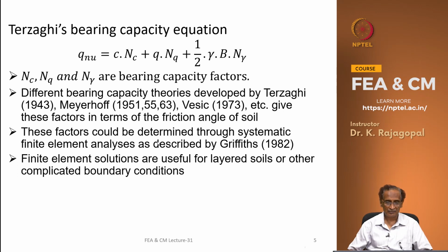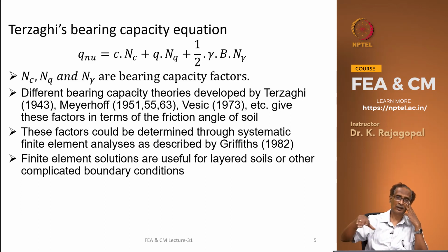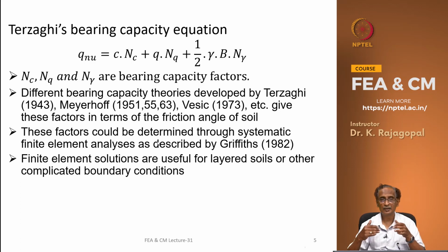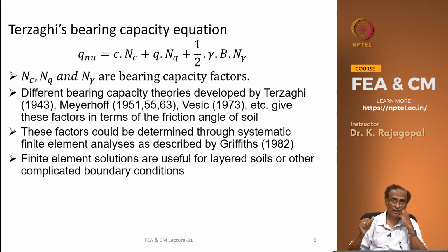And this finite element analysis becomes necessary if you want to analyze a layered soil profile, or let us say your soil profile is highly complicated. You have inclined soil layers and some joints and so on, and you want to know what is the effect of any footing constructed on such a soil.